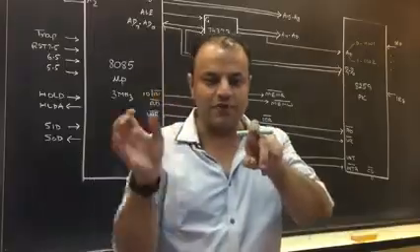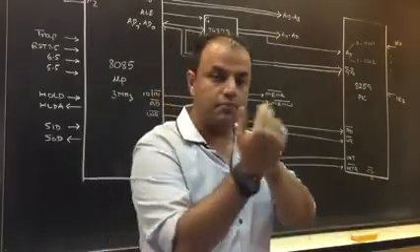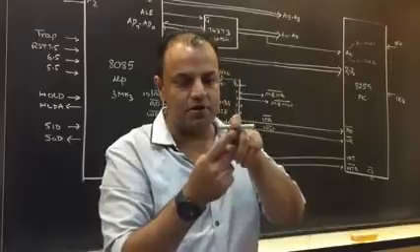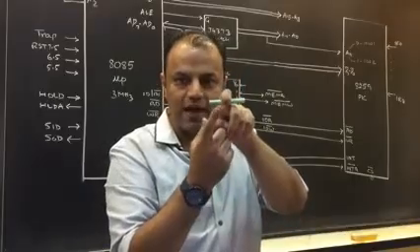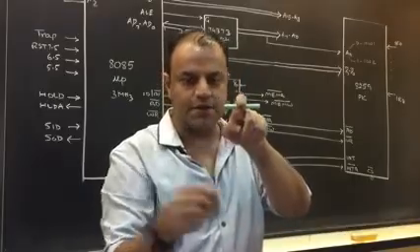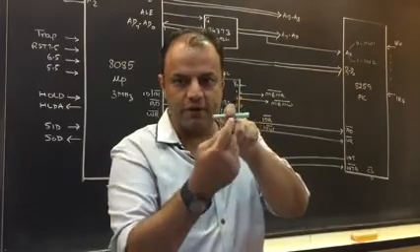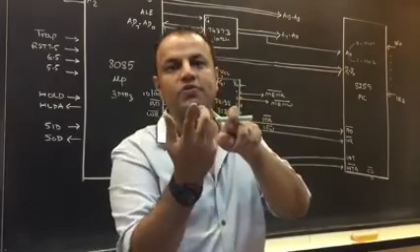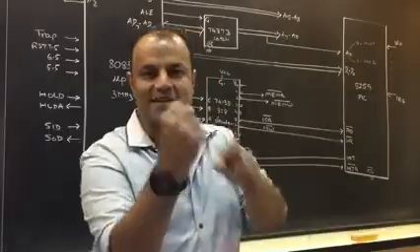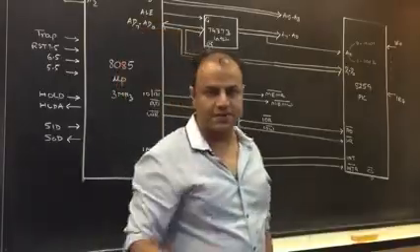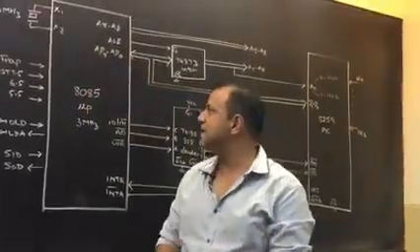All that it did was input is equal to output. Whatever is the input is also the output. But the important thing is the value also has been stored. It has been latched. Even if you stop sending 25, the bus will now carry 25. Who is sending it? The latch is sending it because the latch has captured the value. Please tell me, did you understand this? Now, how do you use this latch?